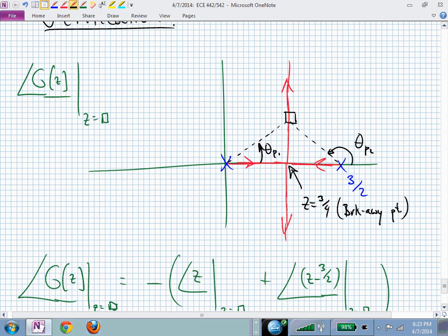So now that's the complete root locus for that system. We have the real line segment, and then we have two branches. What's the pole zero excess for that system? 2. How many finite zeros did we have? We didn't have any. How many infinite zeros? 2. So we expect two branches of our root locus to go off to infinity. One branch is going off at 90 degrees, the other at minus 90 degrees, or 270. Those are our branches going off to infinity.